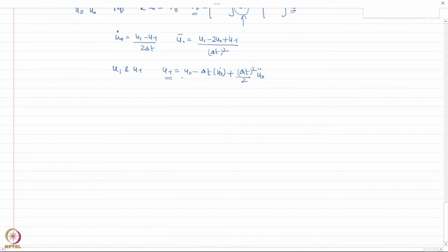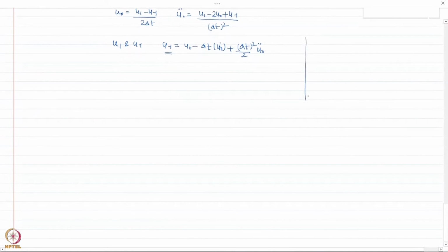and get the response. Now remember how accurate the response would be. Let us say I have found out analytically that the response looks like something like this. Now whether my numerical response, how close it would be to the actual response, depends on many parameters, and one of those parameters is the time step that we use. It can go something like this, it can follow like this. It is always discretized, is it not? Always discretized. So how accurate it is, or how close it is to the actual solution, one of the parameters that determines this is actually the time step.